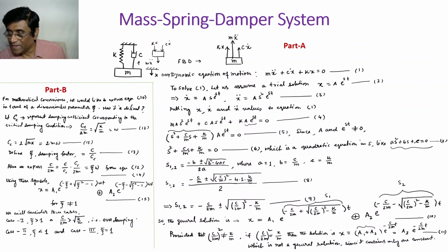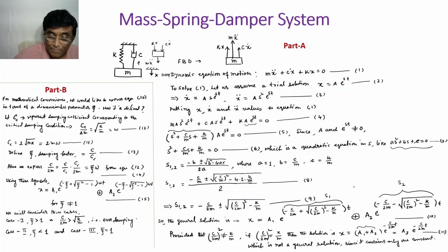Look here. So minus some quantity, which is less than that. So minus this, more negative. So irrespective of whatever values C, M, K are, e to the power minus something plus here also e to the power minus something. That's a great thing of a second order mass spring damping system. As long as these are positive quantities, this is the case, and it has great consequences.